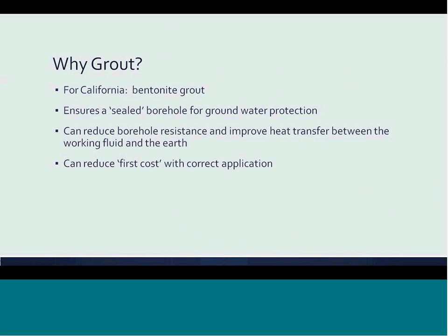Grout requirements vary from state to state. In California, it is required that all boreholes be grouted from the bottom of the borehole to the top to ensure that the borehole is properly sealed. The concern is that if the borehole is not properly sealed, it may act as a conduit between aquifers, potentially contaminating the groundwater. In California, a large percentage of our drinking water comes from these underground aquifers.